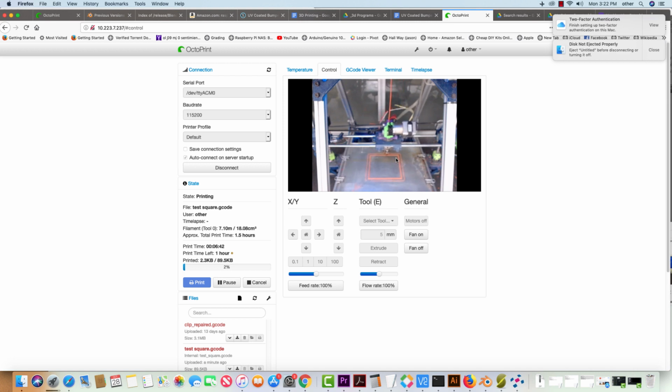But another thing is, it could be the fact that somebody messed with some of the settings over here, making the bed unaligned. It happens from time to time. Please don't ever change the alignment on a machine. That takes a very long time of knowing how to realign a 3D printer. If you're not seeing it extrude the plastic out, come see the instructor, and we can look at it to see if it is in fact an unalignment issue. You can tell that because it will be almost scraping against the platter rather than printing.